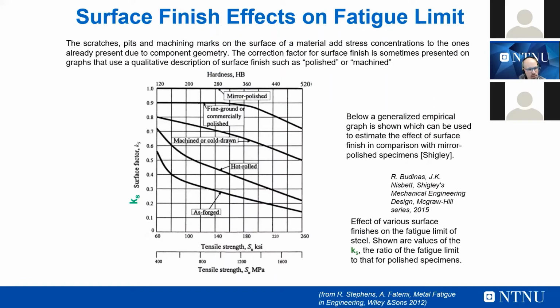Another important aspect that we have to consider for additive manufacturing components is the surface finish effect on fatigue limit. You know that an additive manufacturing component can be printed and used as built, so directly taken from the process, or we can machine it after we have printed it. It's important to understand that this can affect your fatigue life tremendously, and you have to consider this in your fatigue design. Of course,